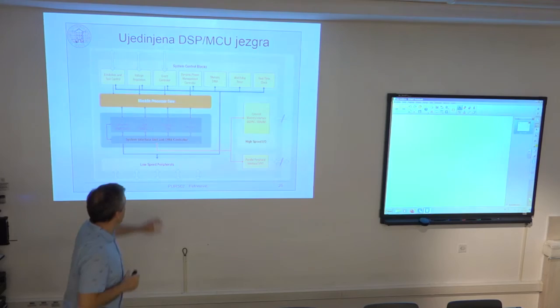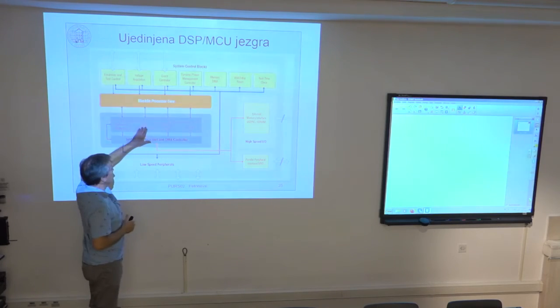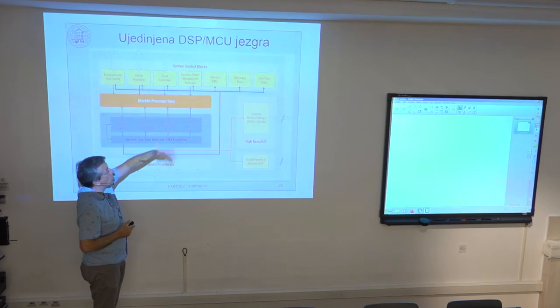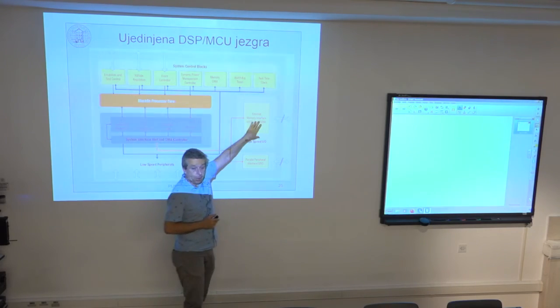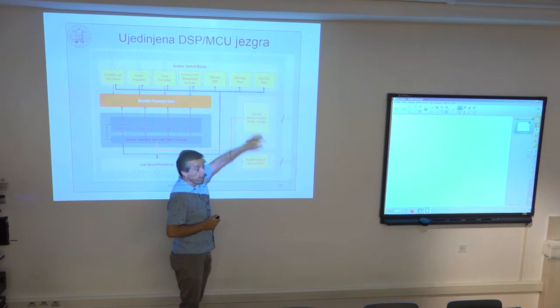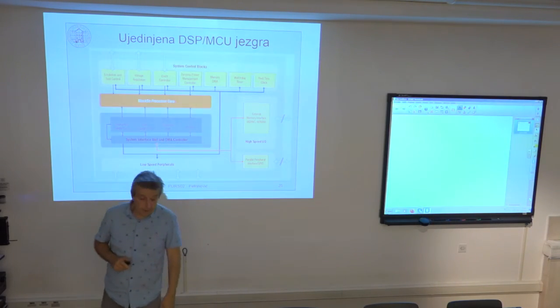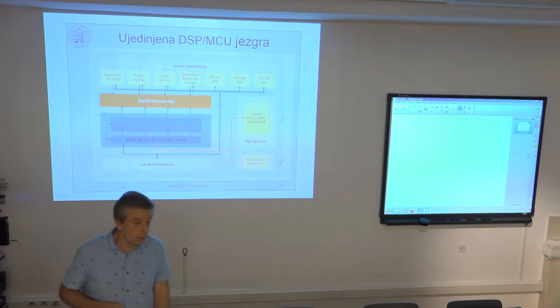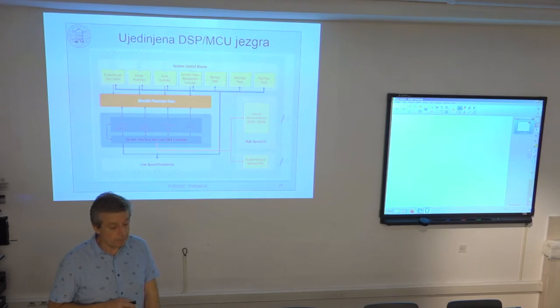And if I'm lucky, if this data value is already stored in this cache, it comes directly from here. I don't have to go into outside memory, external memory. So if it is not contained in cache, then I must activate this memory interface and really fetch the data from, for example, the dynamic synchronous RAM that's connected to this chip.